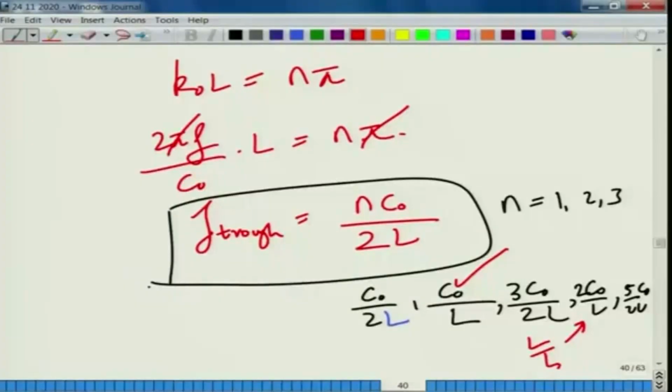And again, because engine noise is concentrated at the first firing frequency of the cylinder as well as its first few harmonics, the lower frequencies are always a priority, and unfortunately most mufflers, at least the reactive mufflers, don't seem to give a very good performance at very low frequencies, unless you of course increase the expansion chamber area expansion ratio. Anyhow, let us get back to our discussion.